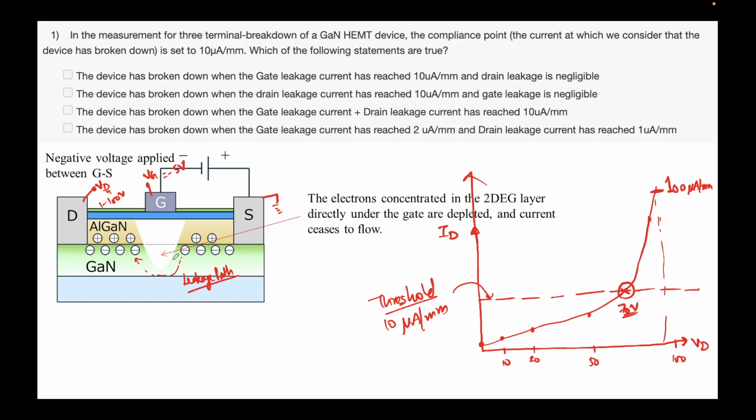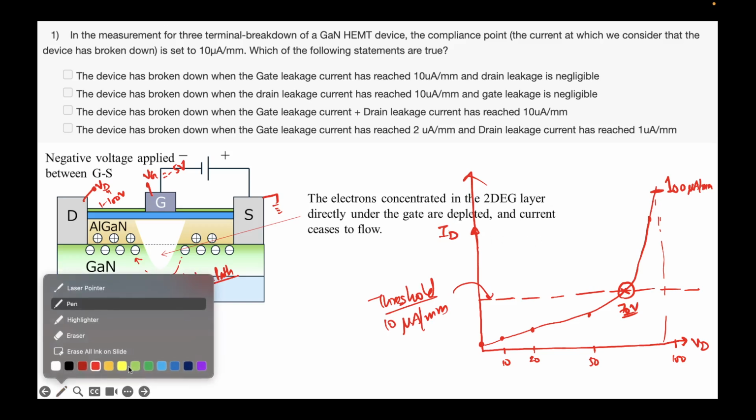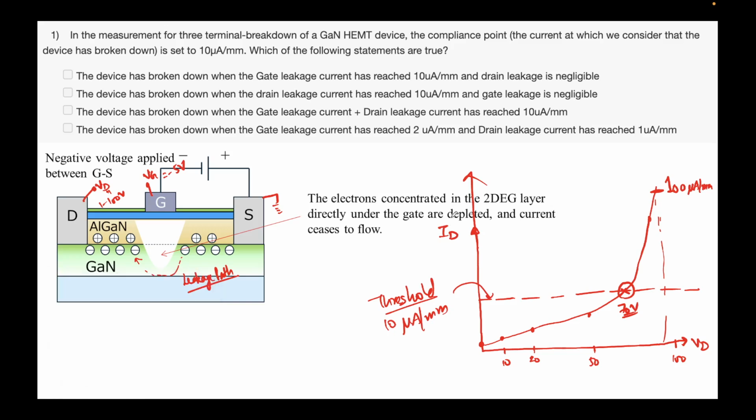Okay, I told you one leakage path. There is actually one more leakage path. There are various pathways that the current can conduct over the surface, not just here but also between drain and gate at the surface itself. Because you're increasing the drain voltage, VDG is also increasing. So the gate current can also increase due to whatever reasons, from here or from here, wherever. So I'll now draw IG in a different color. Now I'm also drawing IG on the same plot. Okay, let's say my IG looks something like this.